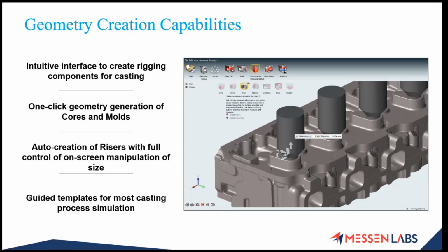Inspire Cast not just helps you to simulate or check the feasibility of the casting process, but also provides you geometry creation capabilities to do minor changes in your model, so that you do not need to take it back to your CAD tool for making any changes. This tool is very intuitive and easy to learn, with just one click for creation of geometry, core, molds and many other components. And just by specifying the geometry, it can automatically create risers and provide full access for manual manipulations. Now let's see which types of casting processes are supported by Inspire Cast.